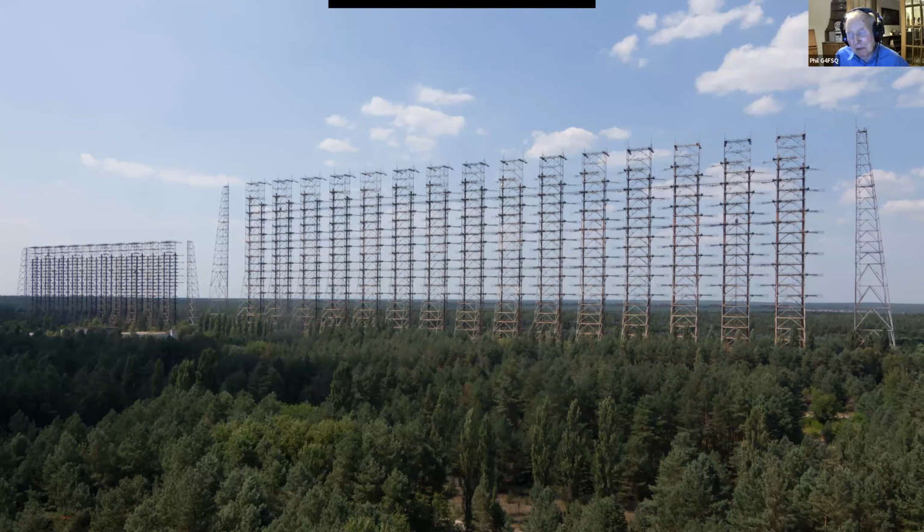I'll just mention that trees are a satellite installer's nightmare. Yeah. You might get a signal through them at this time of year, but if a tree's in leaf, you will get absolutely nothing. I used to use a triangular set square with a line marked on it at 26 degrees and hold it perfectly horizontal. I could then tell whether I was getting the signal over the top of the tree or not. Many a time I've had to put dishes on poles and on chimneys to get the signal over trees. As I say, they are a satellite engineer's nightmare. I know.